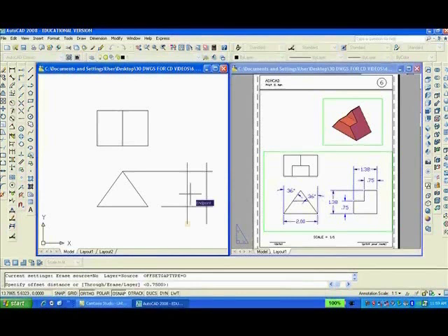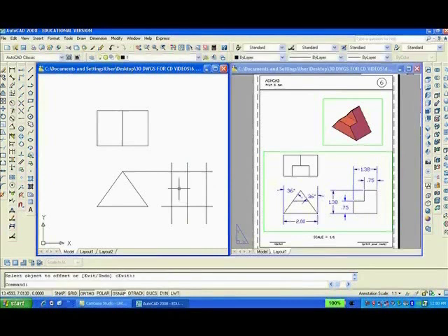offset 1.38, enter, from here over to here. Now I'm going to offset, so I just repeat, hit enter twice. 0.75, enter, and this line goes up. I can type F enter for fillet and clean up. Try it again. F enter, hit escape whenever you're in trouble. I can fillet these two, hit the space bar, fillet these two, hit the space bar, etc.